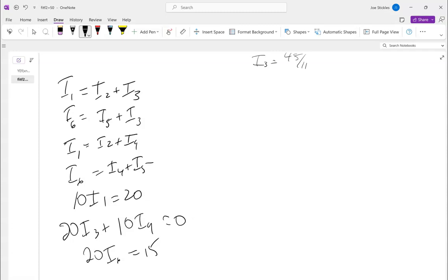Yes. What do you have to do for a given circuit, or is that just not something easily figured out? Since we have 6 currents, we have to have at least 6 equations. Unfortunately, you might get 2 equations that give you the exact same information, like we had here with the 2 nodes. So you make sure that you have enough information, because if you only get 6 equations and you row reduce and you get a row of zeros, you're going to have infinitely many solutions.